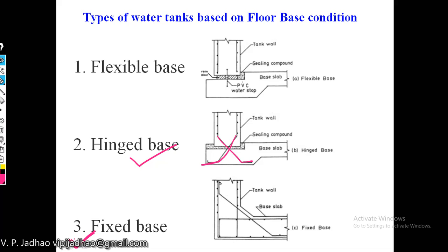So in this type of water tank, all the reinforcement of your wall will penetrate or be provided inside the base slab. It will be provided up to the base slab, due to which some bending moments will be developed in this wall. So as per our syllabus, we will be studying the design of water tanks with flexible bases.